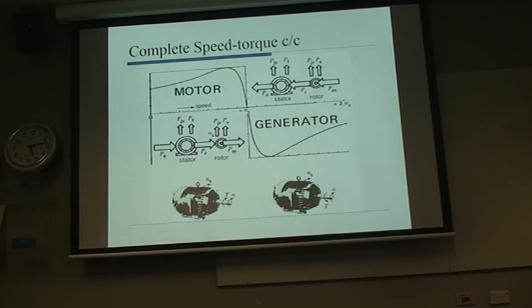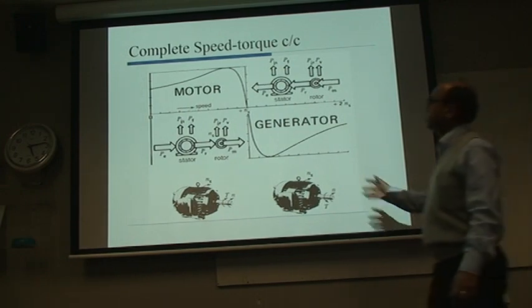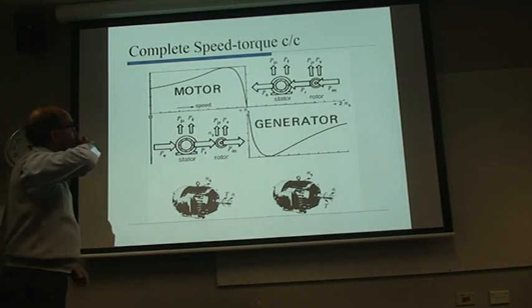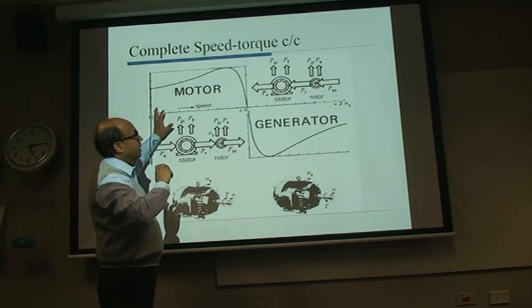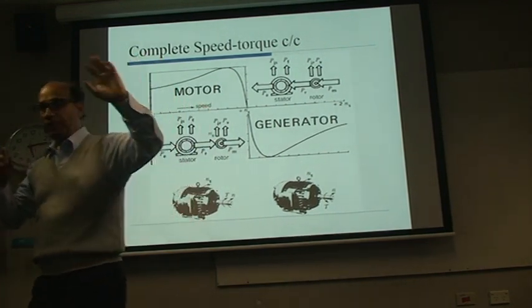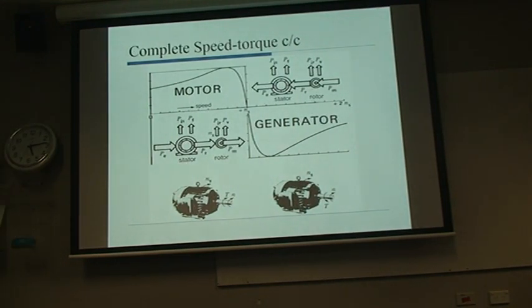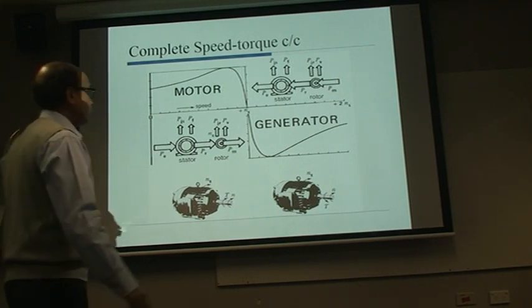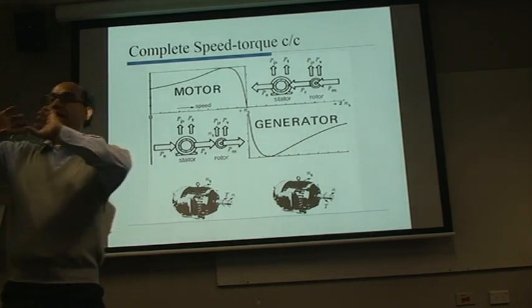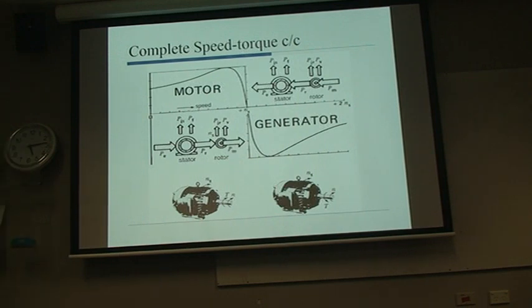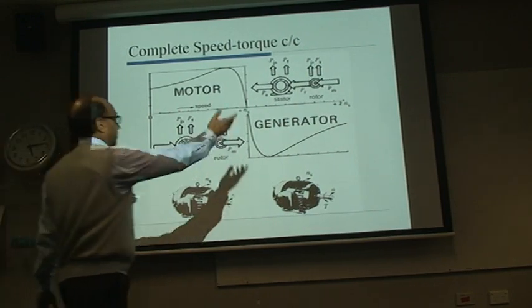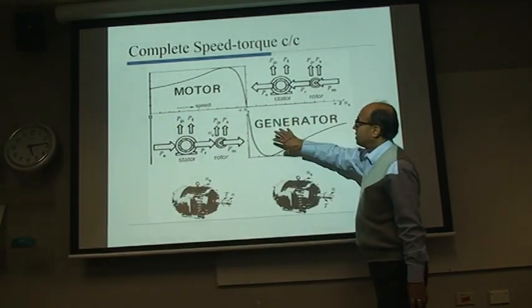So that side is usually the motor, but sometimes you can actually run the motor, induction motor, as induction generator. Okay, so if you want to run the motor as generator, of course then somebody has to run the rotor. Usually you have seen wind power. Wind power, the machine is the induction generator. Okay. So then it reverses the characteristics.